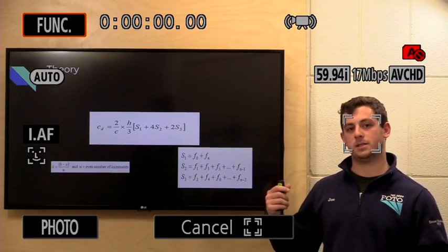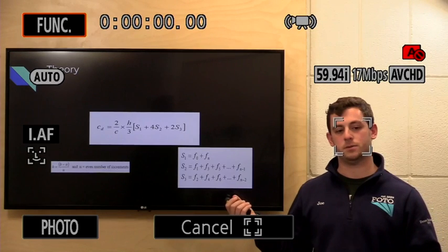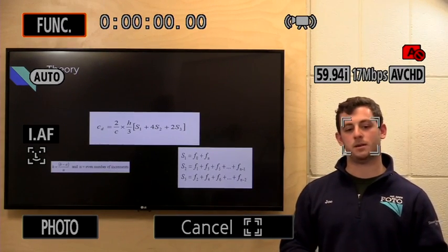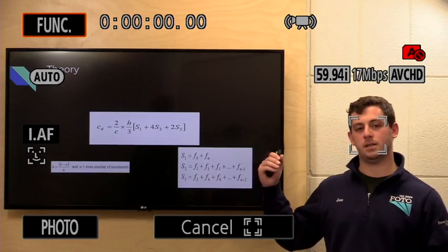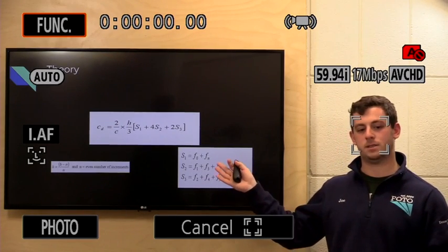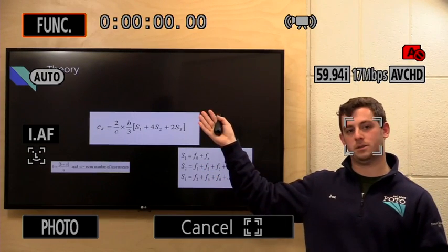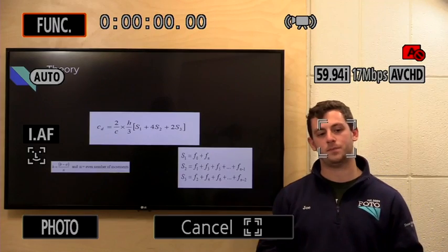So all these integrations of Simpson's rule then come into our coefficient of drag, which is simply calculated here by taking each of these integrations into these values S, which are then multiplied into our coefficient of drag calculation.